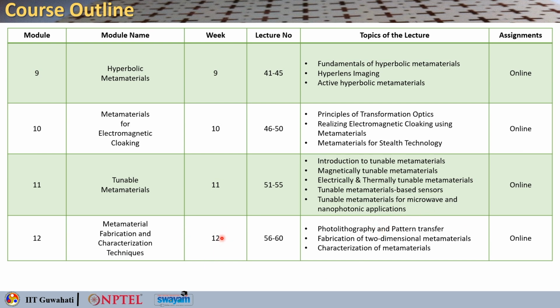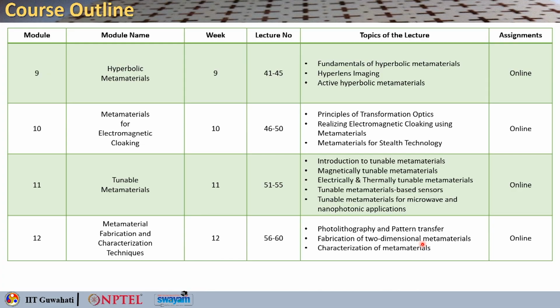And in the final week, we'll be covering module 12, which will focus on metamaterial fabrication and characterization techniques. That will tell you how you can actually make those metamaterials using photolithography, pattern transfer. You will also discuss the methods of fabrication for two-dimensional metamaterials and how you can characterize those metamaterials.